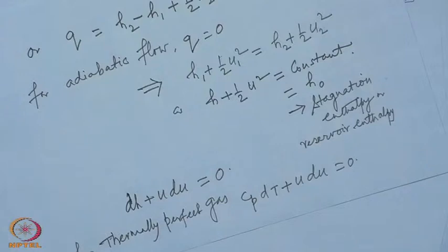The equation can also be integrated if the specific heat at constant pressure is known as a function of temperature. So, assuming that the gas is calorically perfect, where Cp is independent of temperature, this can also be integrated.